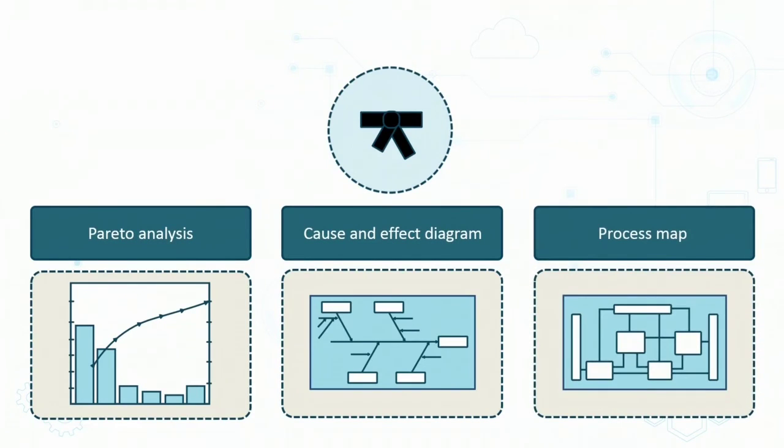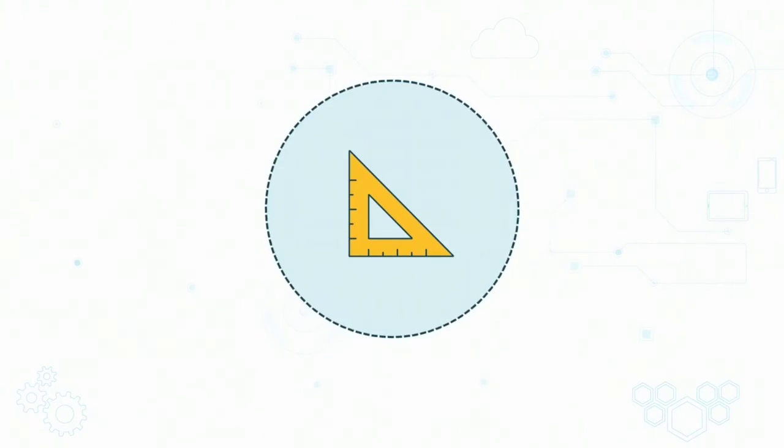Next, the team created a process map and drilled down. Team members identified 20 separate steps involved in brazing, such as cutting a piece of tube, installing it, and brazing it to the return bend. Having focused on the brazing process, the team mapped out the steps and spent 2 days making hundreds of measurements for each of the 20 steps involved.